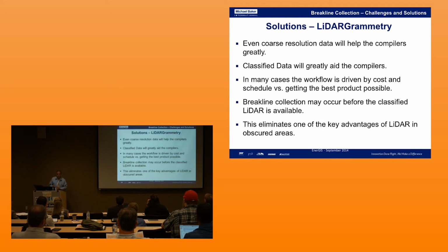The second product will be, I can classify the LiDAR data. That means I can go through the process of automatic and manual extraction of ground points. And once I create the ground points, I can create the intensity image from the ground points. So I can create two different intensity images, one containing both the ground and non-ground points, the other only containing the ground points.